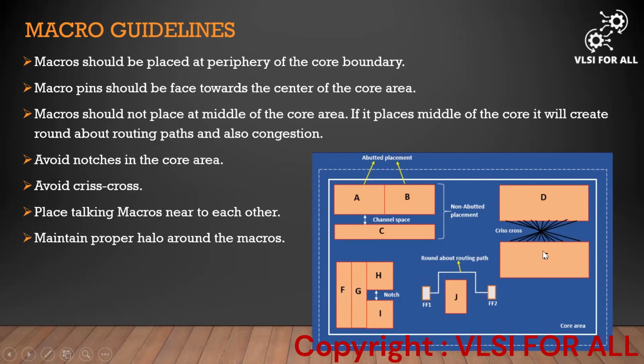Avoid crisscross. Crisscross means, while placing macro to macro, we will look at the macro to macro communication. It has to be a linear communication. It should not be like this communication. If you see, this is the crisscross connection. It should not be present like this.